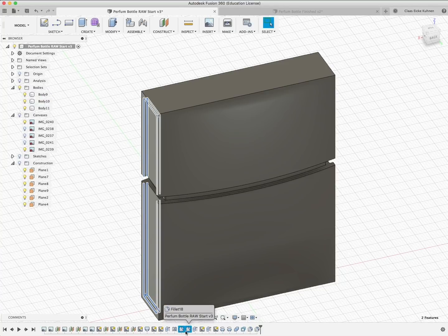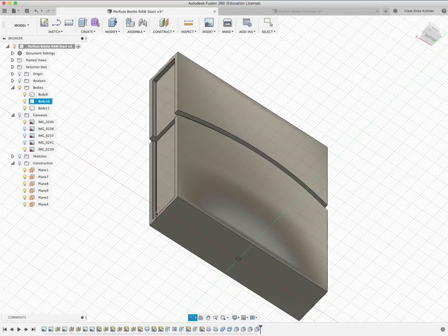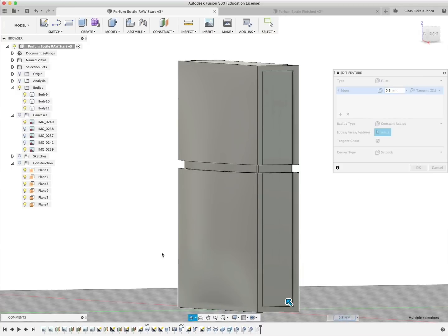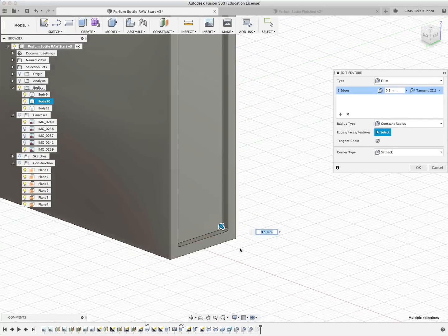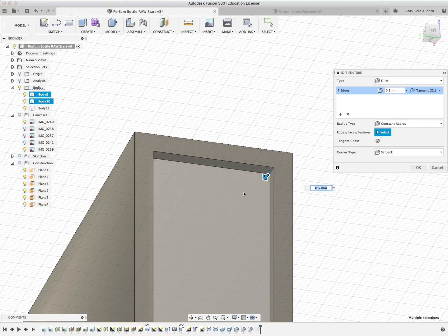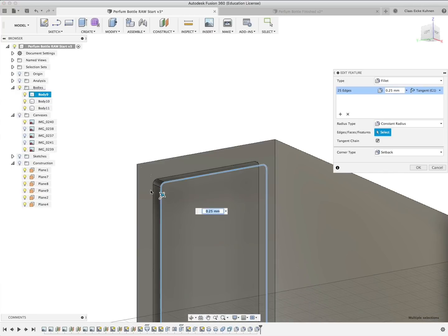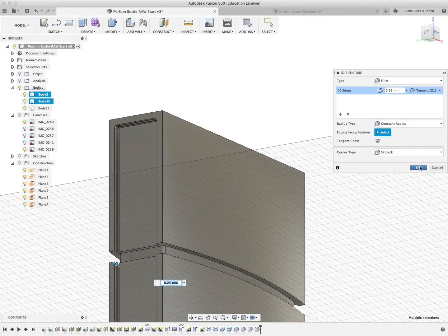And this is already one of these areas where you have to keep in mind, if you design this object, it's one thing, but if this is a collaborative project, you might really want to structure your process in a very logical way. So it might be better to put actually these fillets rather at the end. So I have everything actually set there. I will put in also here the missing edges. So this one and this one. This is actually the nice part about these features where you can modify these selections. And then also here I have to add those to it. Very good. Yeah.